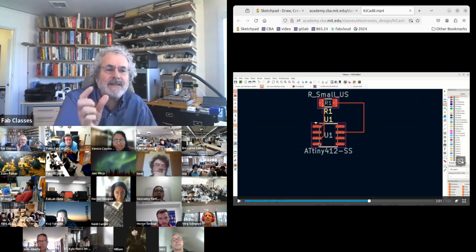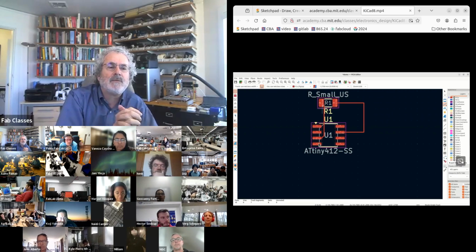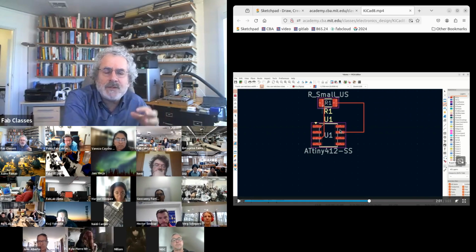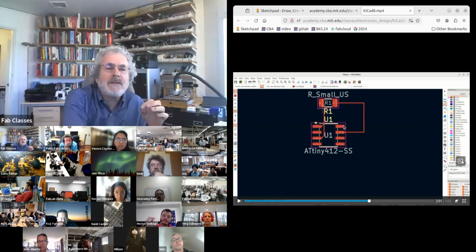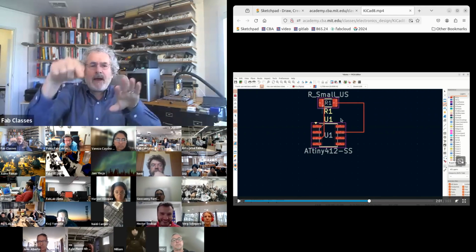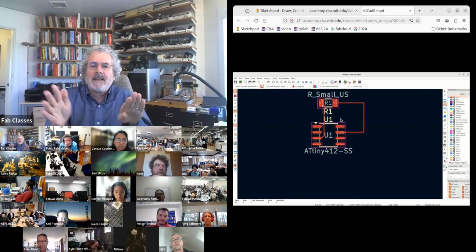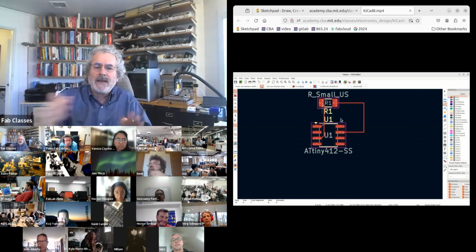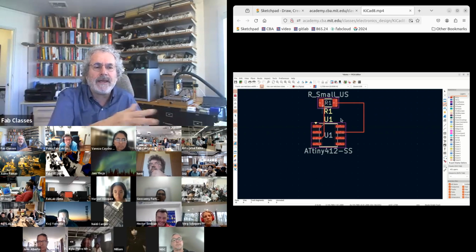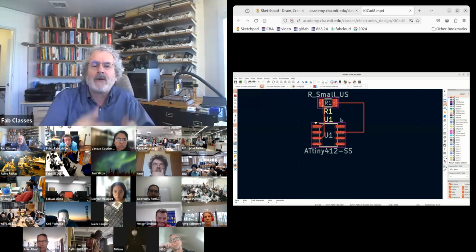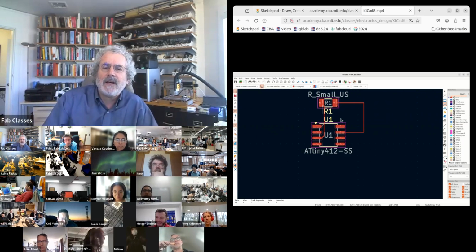And then when I did it, there's something subtle happening, which is you can't quite see it in the video, but when you use it, you'll see zoomed in. Each of the pads and traces has a boundary around it, which is your design rule clearance. That's how close you can come. And so when it routes the trace, it does it with staying outside of those boundaries.